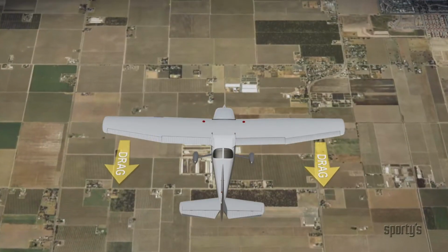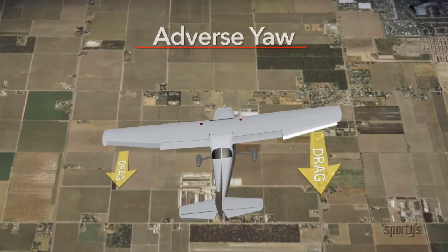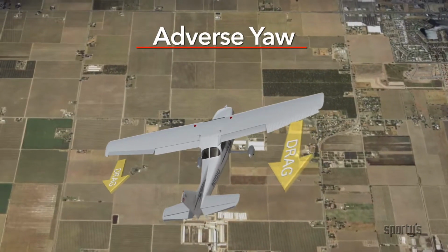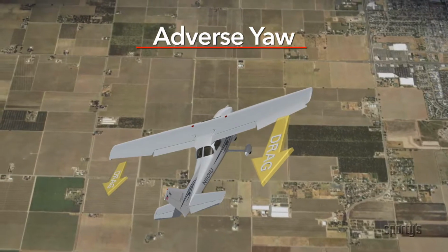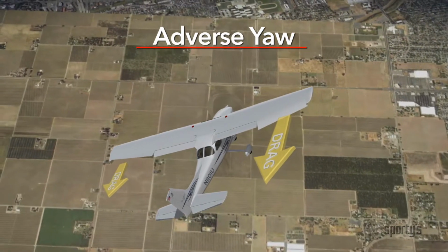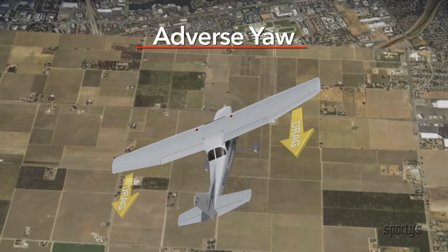The drag or retarding force is greater on the wing with the down aileron, causing the airplane to yaw to the opposite side of the bank. This tendency to yaw opposite the bank is called adverse yaw. In turning flight, the rudder's only function is to counteract the adverse yaw, which happens when the airplane is rolled into a turn and when it's rolled back to wings level flight.